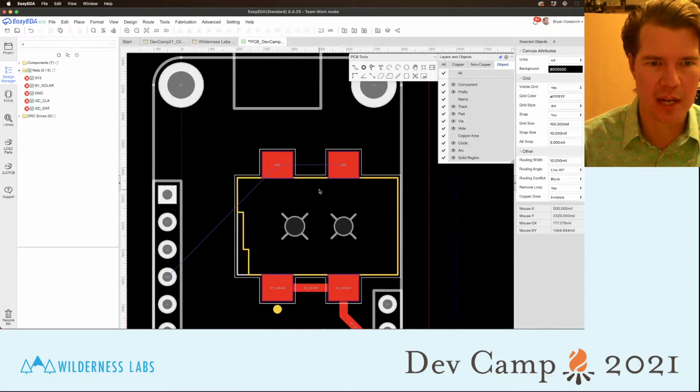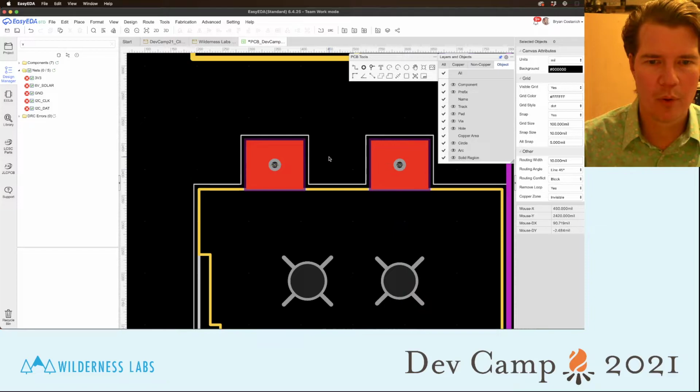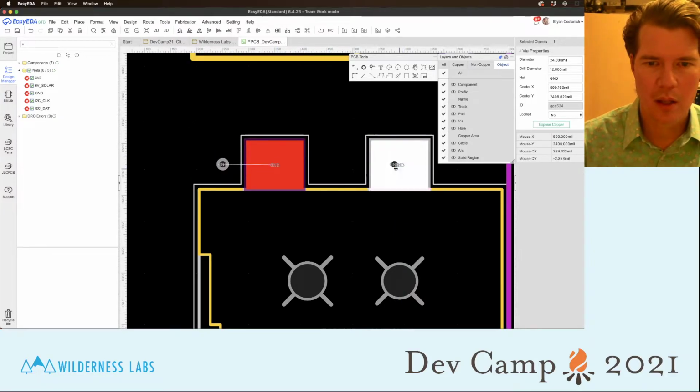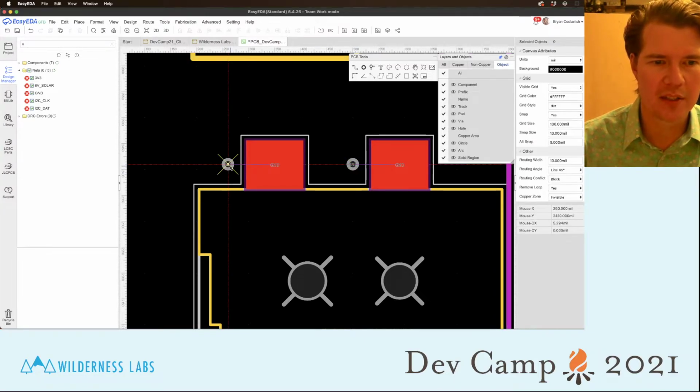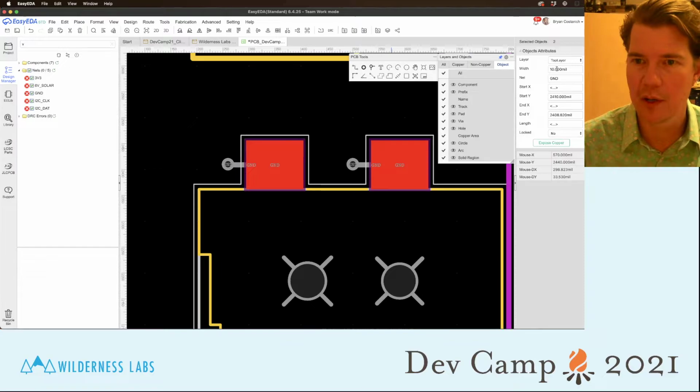And then we need to do the same up here. We need to put vias in for the solar jack, and just as before, because this is a power line, I'm gonna beef these up a bit. I'm gonna beef this up to 30 mils, not millimeters.